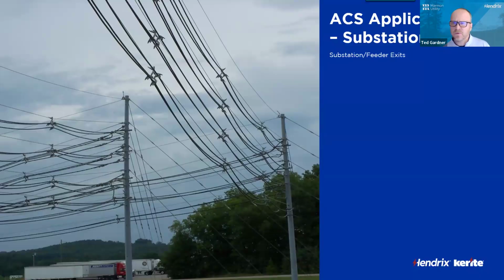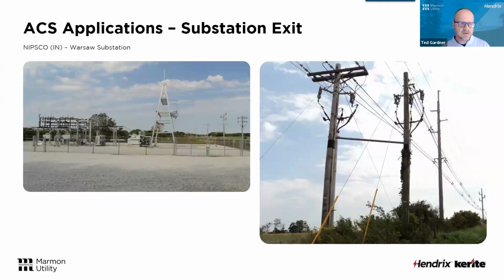There's another picture of some of the corner structures that we do. This is what I call our typical cooperative substation. You've got your 138 line coming in down the railroad right-of-way, goes into the substation. Then they've got 2 distribution circuits that come back out of it. One of the things you'll notice in that lower right-hand corner is we don't need to install those intermittent distribution-only poles. Again, with the size of the messenger, we can span it really as far as we want. So it's a pretty good application for transmission lines.